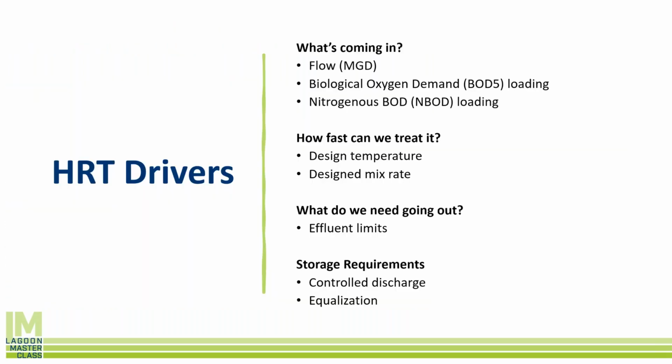So what are the drivers of HRT, or hydraulic retention time? Why do we need more hydraulic retention time in some cases than in others? And that is what's coming in, how fast can we treat it, what do we need going out, and storage requirements. So what's coming in? If flow increases, it's going to bring more loading with it. We may need to hold on to the water longer.